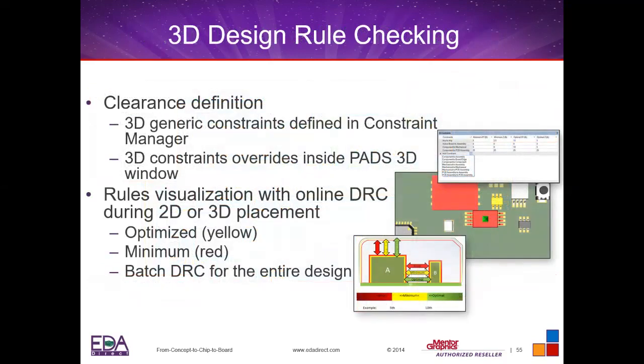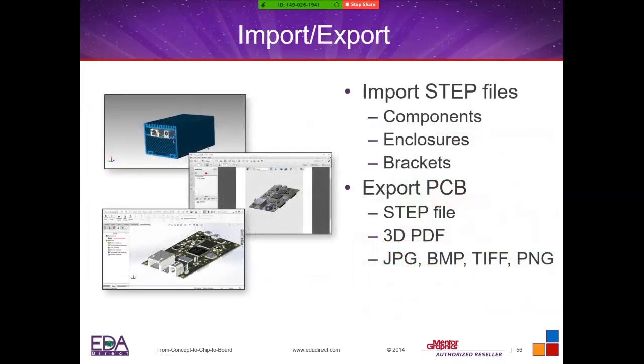You'll have a 3D design rule checking that's going to come with the tool. So this is actually very nice. Rather than bothering your mechanical group, asking them to give you the enclosure that the board's going to fit in, you can actually run DRC checks in here to find out, are you having component issues with maybe them being too close to the enclosure? Do you have enough spacing in between the components, whether you're reflowing or soldering components on? So there's a full DRC spacing check that you can run in the tools. You'll also be able to import and export the data.